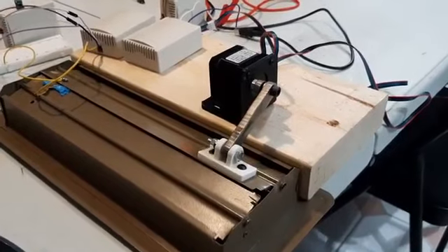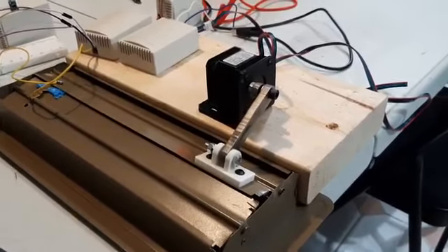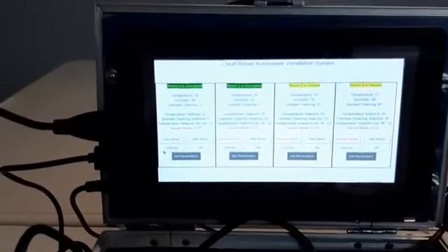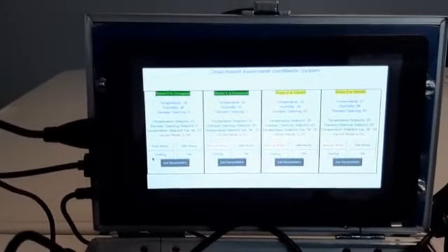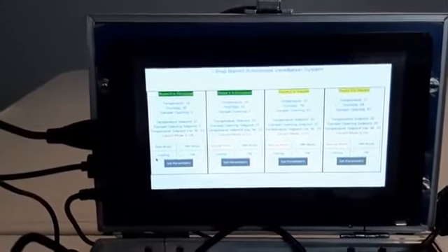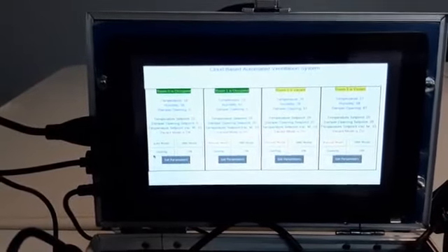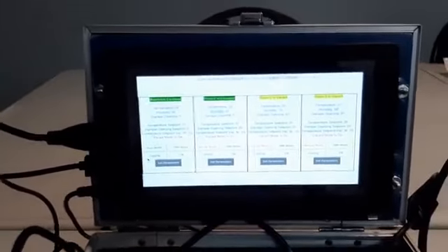And now the damper is fully closed, and the damper opening has to be 0% on the monitor. So you wait for the monitor to update the information, and it shows 0% now. The damper is fully closed. So it shows that this system works for both heating and cooling mode, in auto mode and manual mode. The on-off button works, and the set points can come from HMI or from the app. I will show the app as well, how to change the set point values and how these readings can be shown on the app as well.